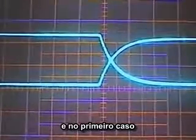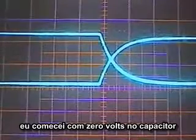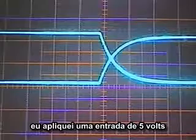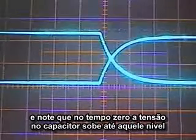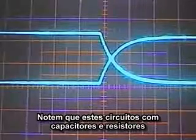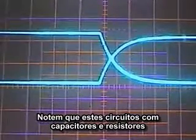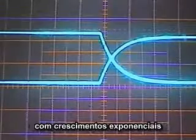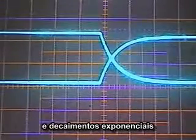And in the first case, I start with 0 volts on my capacitor. I apply an input of 5 volts, and notice that the capacitor rises up to that level. So notice that these circuits with capacitors and resistors are typified by waveforms that are exponential rises and exponential decays. Okay, we'll see more of that next time.